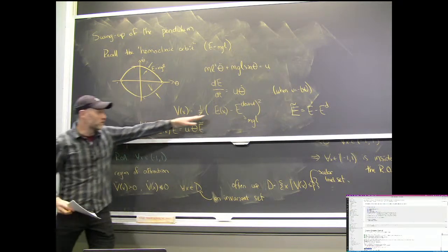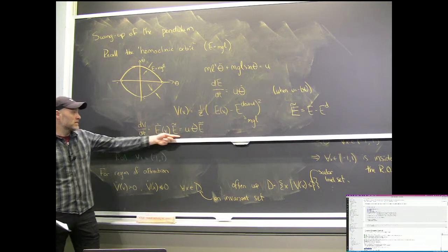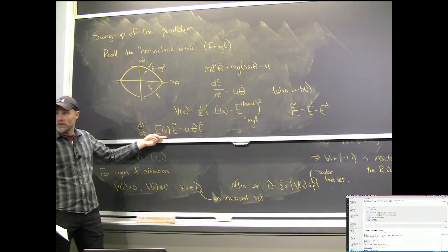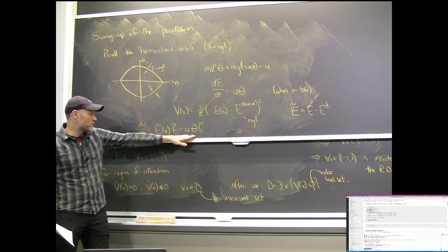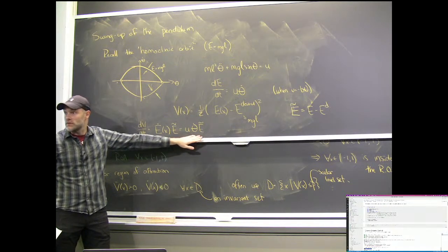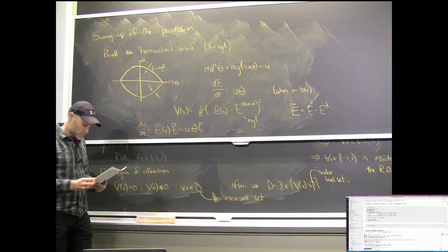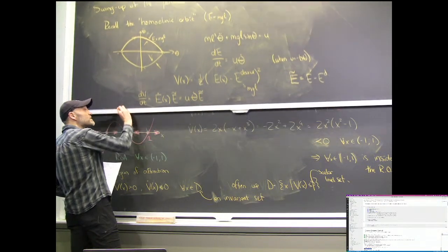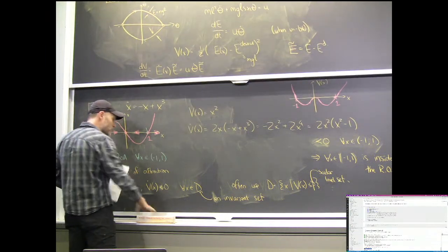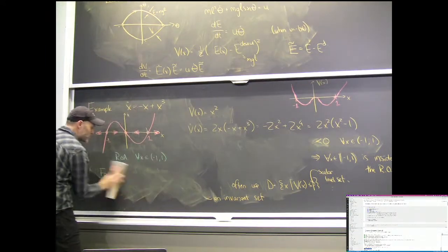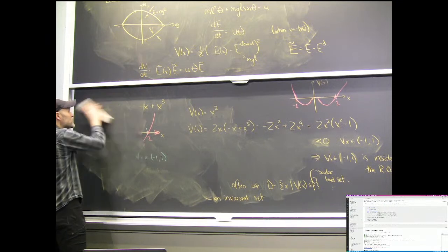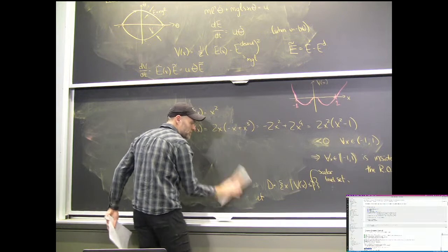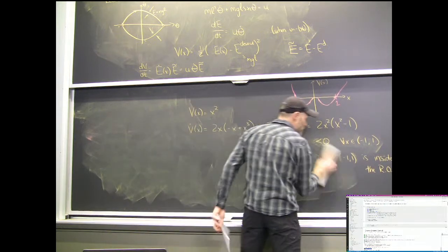That's just taking the gradient of this, multiplying it by my E dot, which I learned about, and the form I get is simple. So sometimes the Lyapunov function just almost tells you the control. So I can choose a control that makes that a valid Lyapunov function over some domain.